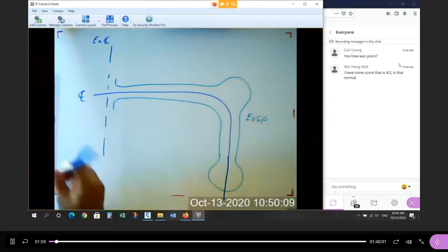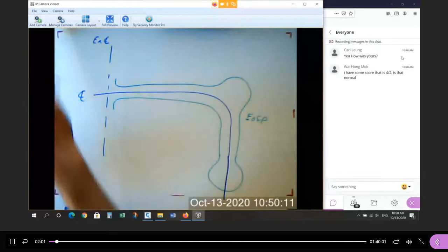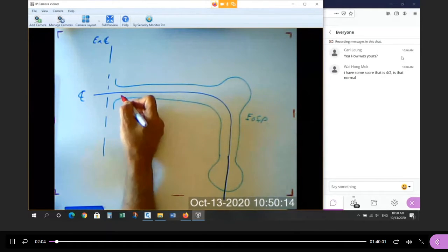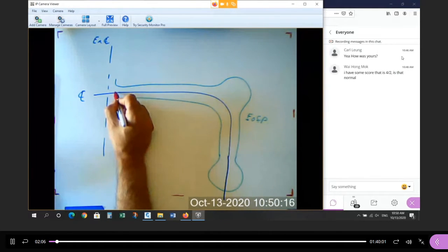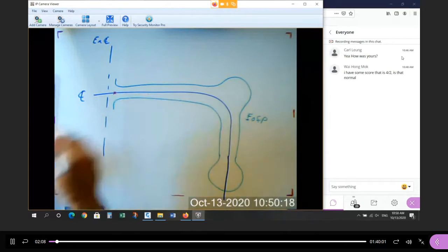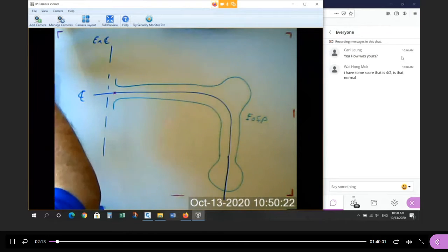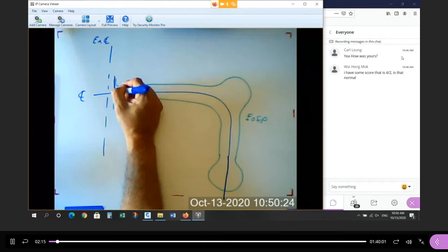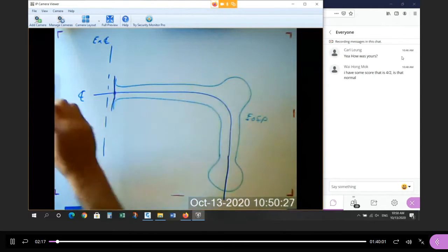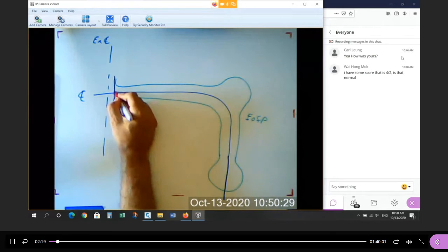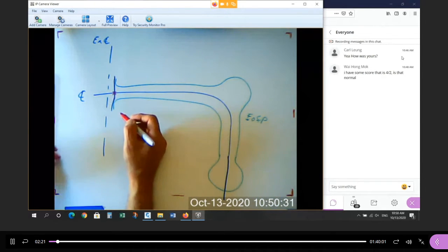So what we did was we determined, so I can do this in red, of these 2 points. Actually, we need the station value of the edge of asphalt on the existing road, right? So there's an existing edge of asphalt through here. We need that station value, so that's our first station elevation.